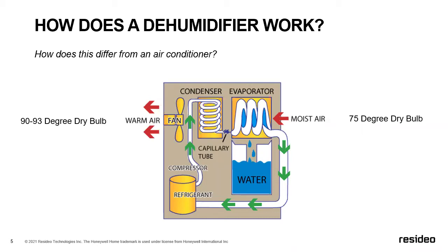If we get a good temperature rise in the 15 degree range, we can then know that our appliance is working. And from that point, if we're not meeting the expectations of the consumer or even the application, what we thought we would achieve from a humidity standpoint, we would then probably shift our attention to how it's ducted and how it's controlled. And we'll talk a little bit about that as we move forward. So hopefully that gives you a good understanding of the anatomy and function mechanically of our dehumidifier.